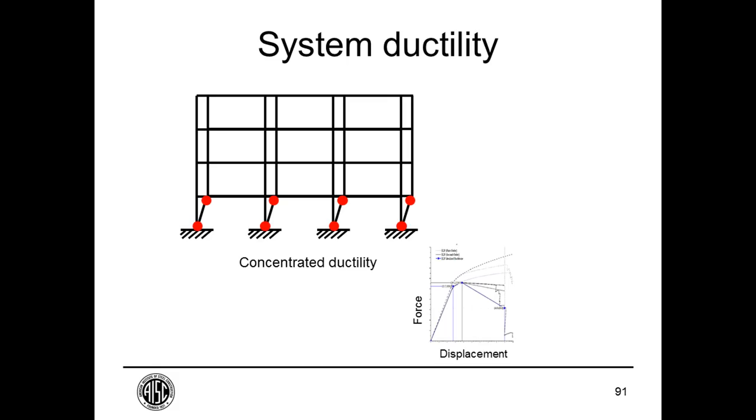to validate a design. So if you had a 4, 6, or 7-story office building, and perhaps your design was finished and your owner was ready to build it, the owner now had to face a testing requirement, and the owner maybe wasn't interested in testing 7, 12, or 15 different beam to column combinations. And so instead the owner said, well, let's just make them all the same W36 beam, and we'll test that, and if that works, we'll use it everywhere.